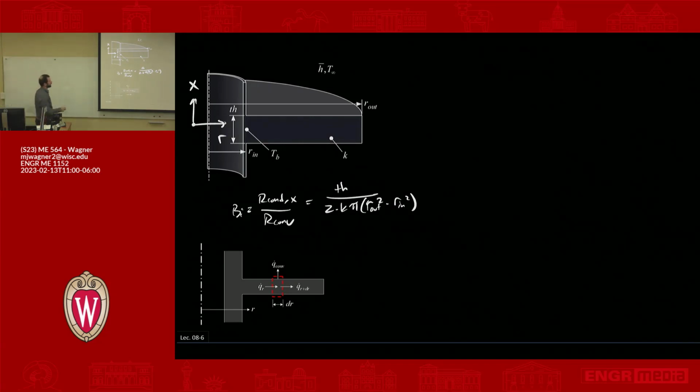And again, what are we assuming here? We're assuming that our worst case scenario is heat flowing from the center line out. There would never really be a case where you'd have heat flowing from the top surface to the bottom, because of the symmetry of the problem. So we're just going to say it flows thickness over 2, and then the area that it has to go through to get out is just one of the disks on top. Okay.